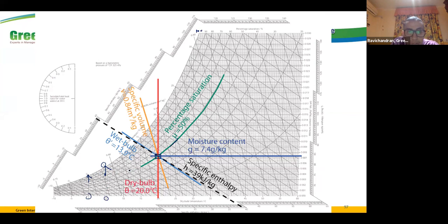So where is enthalpy? We can't neglect it from the chart. No, this is one of the major things in the chart. It represents the energy of the point. So it's very important. There is no psychrometric chart without enthalpy. So how do we present enthalpy? We present enthalpy by an external scale. This scale is on this side and the other scale is on this side. This scale starts from -10 up to the maximum here.